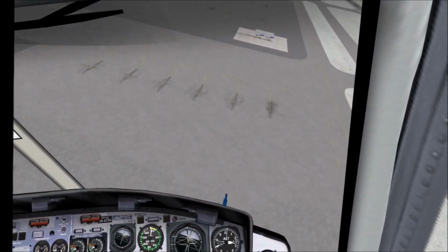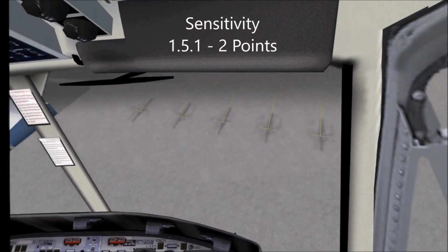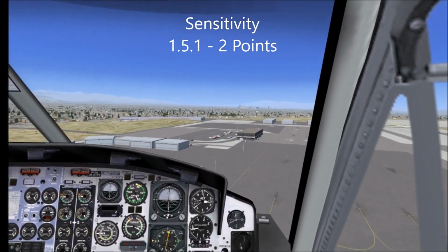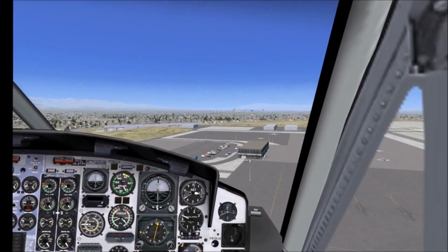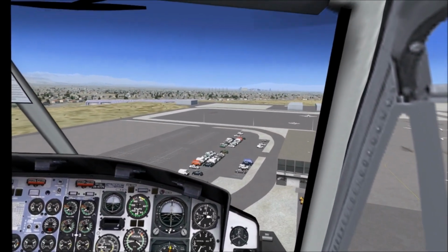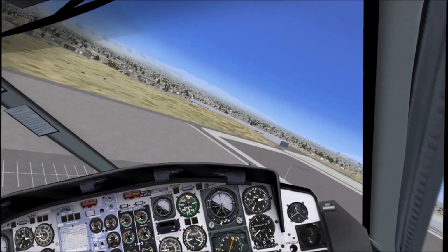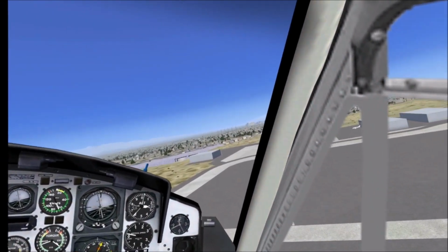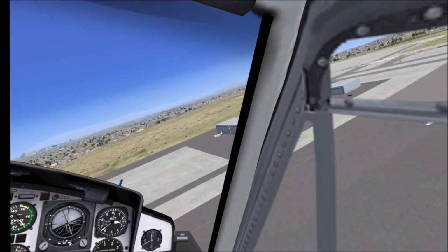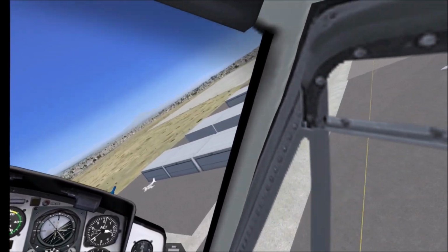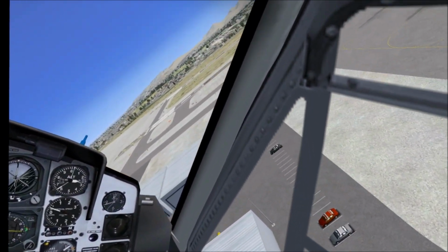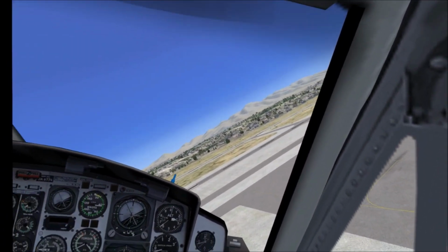Pitch seems to be okay, but in roll, oh, see, I was holding that aft cyclic there, and it took a long time for that nose to come back up. So pitch is a little bit better than the roll axis, but even then, in any other model, in any other platform, I can do the same stuff without going full throw on the cyclic. So I can't really give full points for that.